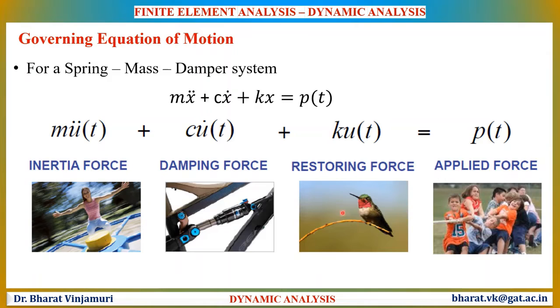The final induced force in any dynamic system is due to the elastic resistance in the system, and this force is a function of displacement and stiffness of the system. Such a force is also called the restoring force, or occasionally the spring force, or the elastic force. The applied load is presented on the right side of the equation, and it is defined as a function of time. This load is independent of the structure to which it is applied.